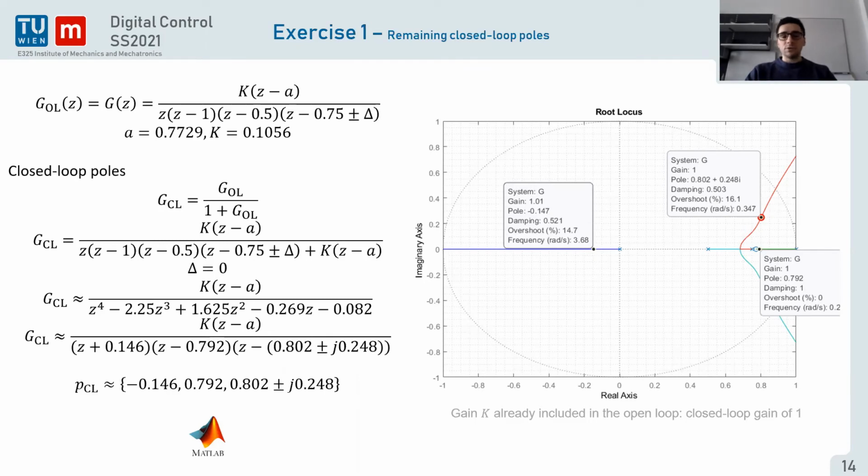If you use a PI controller, for example, using the root locus method, this zero of the plant will stay at the same location and will cause the system to not behave as expected. That's why we can, for example, use a model following controller that we will see next week to kind of remove this zero of the system to have exactly the PT2, or to get much closer to the PT2 behavior.